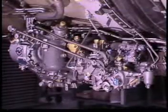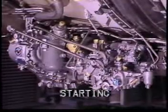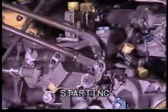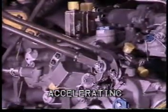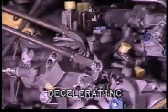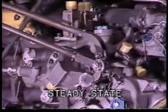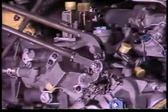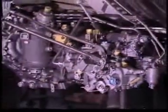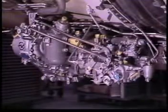The computing section determines the fuel schedule for all engine operating conditions, such as starting, accelerating, decelerating, and steady state. It does this by the integration of 8 input senses which combine to determine the throttle valve position. These 8 inputs are